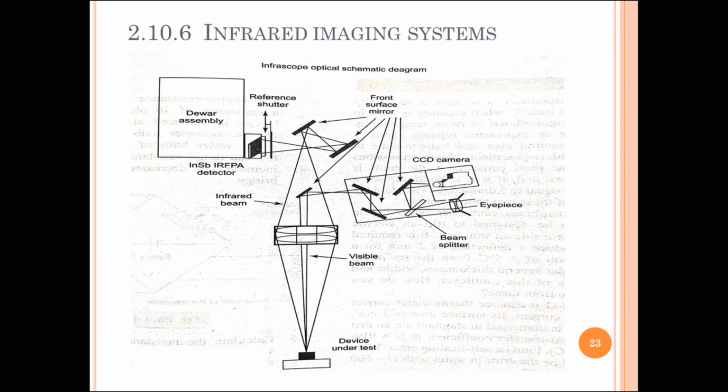While infrared instruments which measure a point target meet many application needs, sometimes the temperature distribution along a selected line or over a selected area is more useful. Line scanners use a single detector and a rotating or oscillating mirror to scan the detector's line of sight over the target surface, giving the temperature distribution along the scanned line. Such instruments are particularly appropriate for moving targets such as webs of plastic film or huge rotating cement kilns.